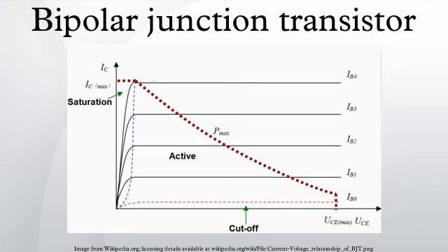The collector surrounds the emitter region, making it almost impossible for the electrons injected into the base region to escape without being collected, thus making the resulting value of αF very close to unity, and so giving the transistor a large βF. A cross-section view of a BJT indicates that the collector-base junction has a much larger area than the emitter-base junction. The bipolar junction transistor, unlike other transistors, is usually not a symmetrical device.